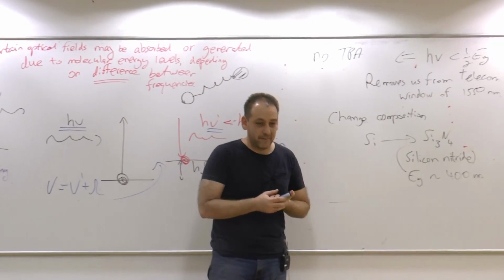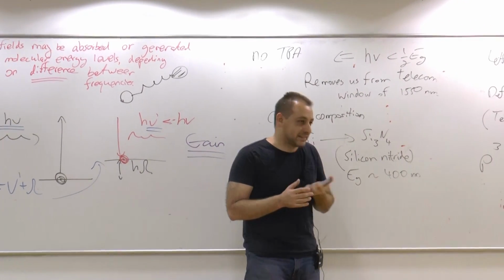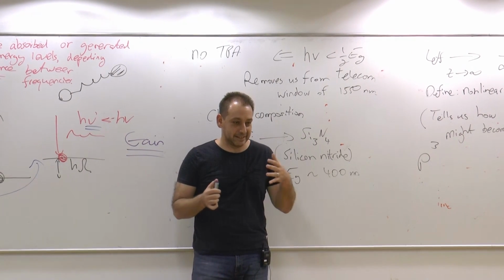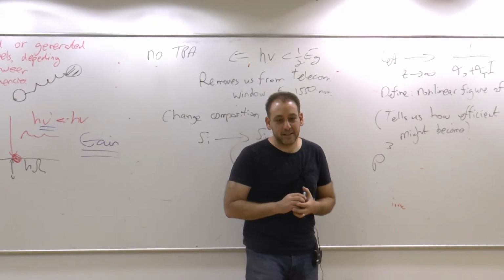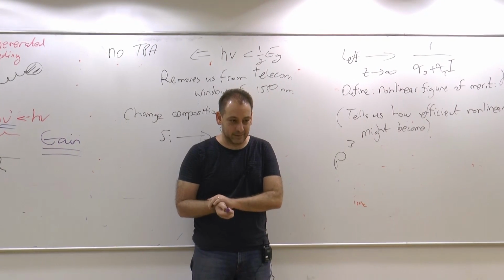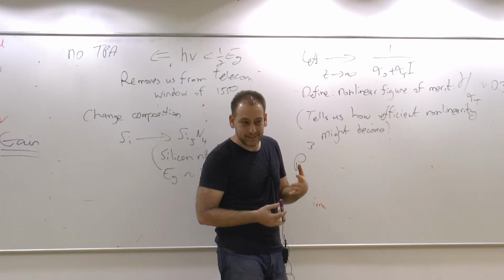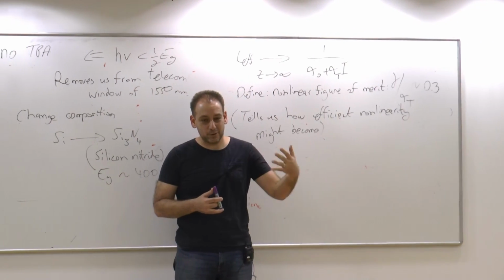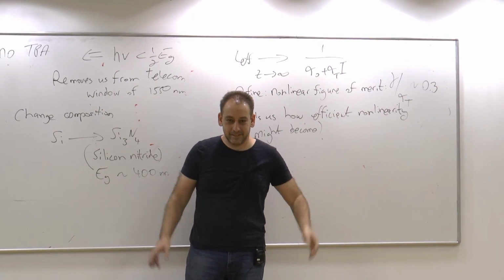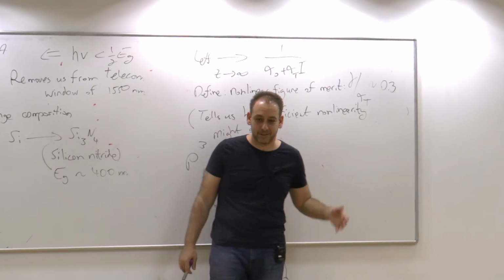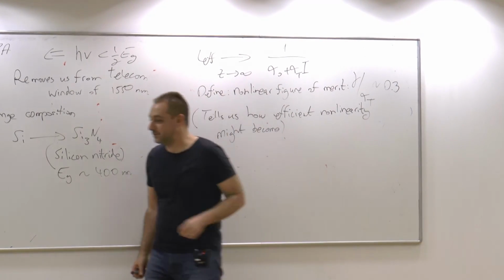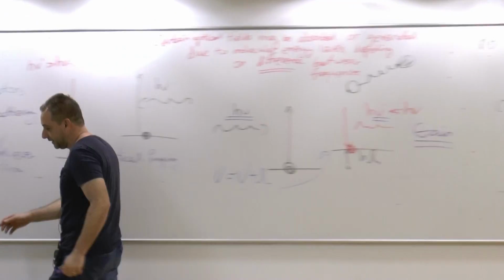And it's a good question, and it is perhaps why, at least I'm not aware of any use of a silicon Raman laser in any device, in any system, in any data center. It remains in the part of the discussion of the papers and of the physics, brilliant physics. Again, you cannot yet fully appreciate the entire scale of complexity involved, but it could not cross over from research to systems because of the nasty fact that you need another laser to get the process going. Questions? Okay, nevertheless, I want you to know that this effect is available.